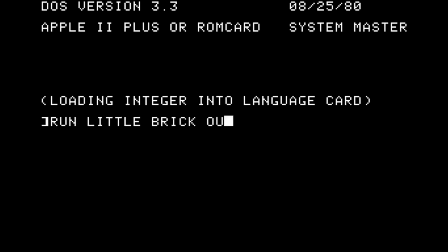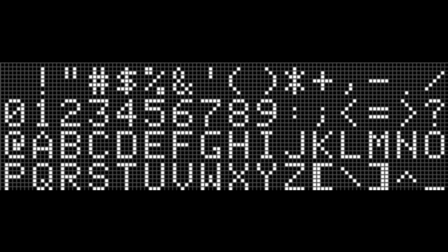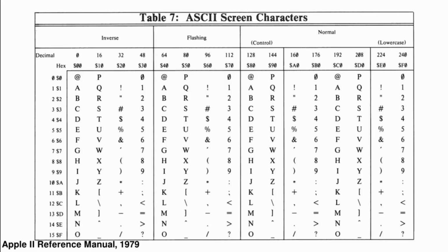The Apple II has 3 video modes. Everything is derived from the 40-character by 24-line text mode. Text mode characters are 5 pixels wide, 7 pixels high, and are displayed in a 7 by 8 pixel grid. 8 pixels high is a natural choice because 5 by 7 characters are attractive looking and because it's a power of 2. 7 pixels across will turn out to be both brilliant and very awkward. Each of the 64 possible characters is represented with a single byte in memory. The extra 2 bits control 2 character attributes, inverse and flashing. 40 times 24 is 960, a little shy of 1K.